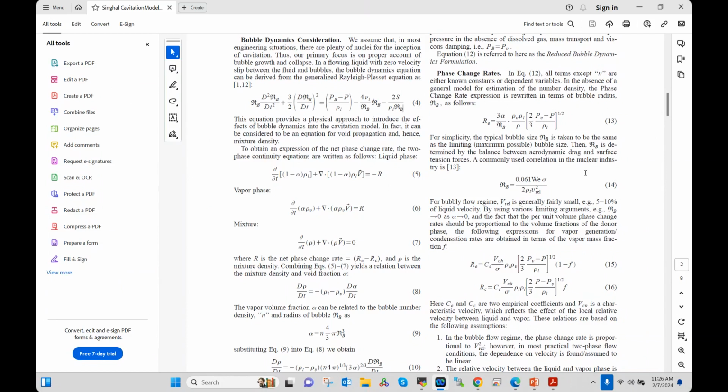So Hannah Boland, Simerics utilizes the Singhal cavitation model. It has some other numerical references from the Schnerr-Sauer model in the way the bubble dynamics are handled. The Singhal cavitation model treats the fluid as homogeneous, while Schnerr-Sauer has been applied as either a homogeneous model or Eulerian phase in the past. Yes, I think Hannah is perfectly answering all the questions.